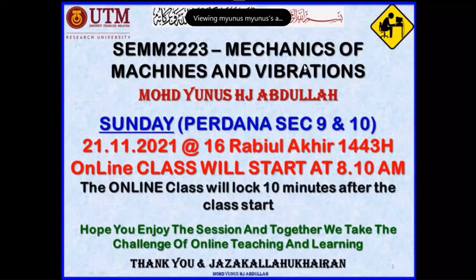As you remember, what we learned earlier was on dynamic balancing. We also did the adjustment. Remember, adjustment means that you have to adjust the mass and the position, as well as the radius or eccentricity, or perhaps the space between plane to plane, and put those parameters on the system so that the system will be totally balanced. So that's what we have done earlier.